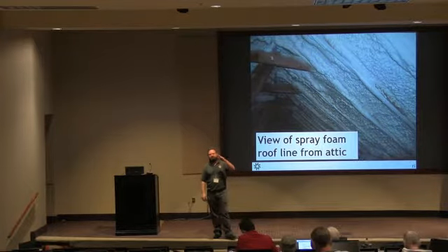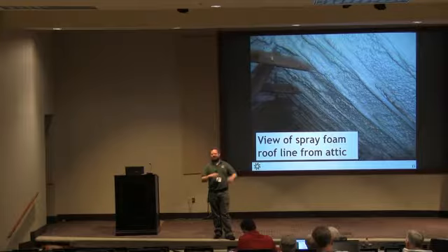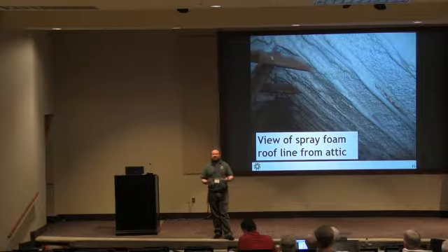What kills a shingle? Excess heat. Heat, right? UV exposure and the thermal cycling, where it's getting baked, then frozen in the winter. Those are the two things. Studies have shown that whether you vent underneath a roof shingle or not actually has very little impact on the lifespan of the shingle. I'm not saying it's no impact, I'm just saying it's very little impact because the primary factors are there anyway.